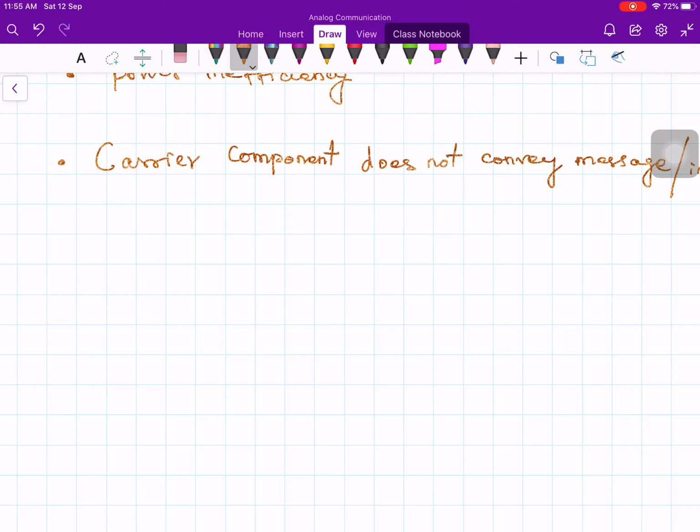I do not require a complicated carrier recovery circuit to produce a local carrier which is perfect in phase and in frequency, I mean synchronous with the received carrier, and that is a real advantage of the AM system. So the demodulation can be effected extremely simply by using a very simple circuit called an envelope detector.